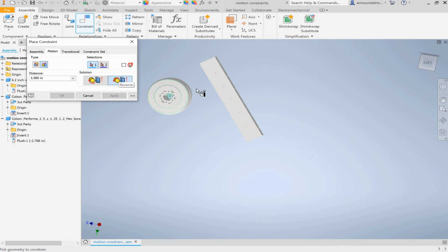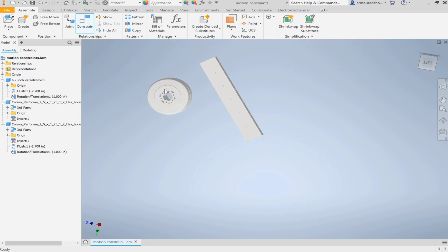Basically, you can see when this goes this way, it'll rotate that way, and when this goes this way, it'll rotate that way. So the first one you're going to select is a face that's going to rotate, and then you're going to select some vector axis that will translate. So I select this, then we apply it. You can see, which sadly, when I rotate this it doesn't translate, which would make it a lot more useful. But when I slide this it will rotate.